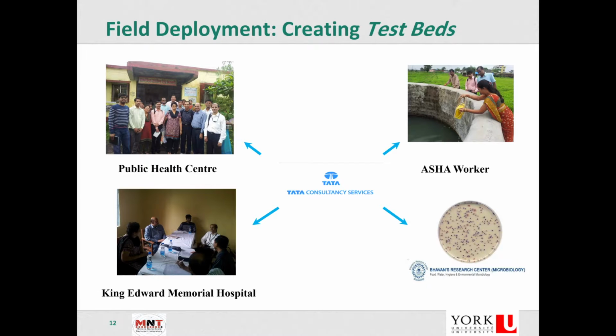To do regular testing, we were also sending water to a regular microbiology lab, because you have to make sure that whatever our mobile water kit was doing, it was doing correctly, so we do a cross validation. In a normal case, you collect the water and send it to the lab. They culture the bacteria, grow it, and then do a plate count. The entire process takes 48 hours, or close to a day or more than a day.